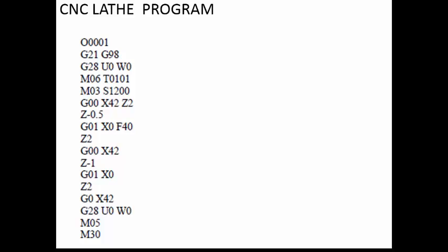The other thing we have to remember is, whenever the CNC controller is reading the program, it reads one block at a time for most cases. It is going to read one block, execute it, then read the next block, and execute it. Like that, block by block, it runs through the program and generates the output, that is the motion of the tool, and we get the required workpiece.